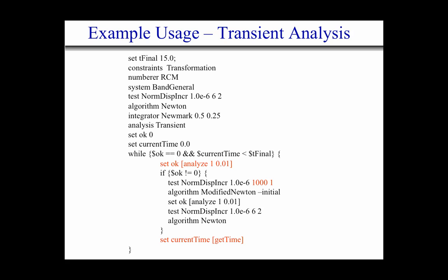If your analysis fails, let's do something. You might think of, well, let's write to a file that, hey, we had problems at this time step. When I'm done, go look at the results after this time step. Do they make sense? Okay? There's lots of things you can do when this thing fails. And there's things you should maybe be putting to the output to remind yourselves that, hey, we had problems here.